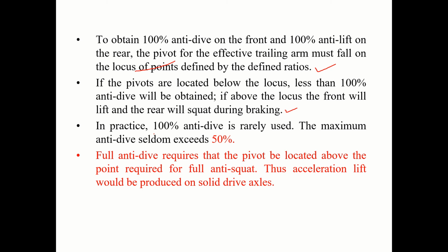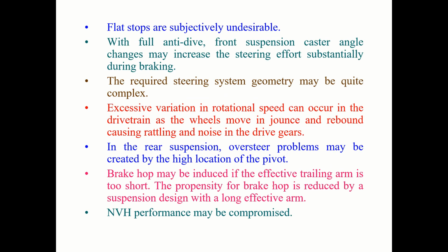In practice, 100% anti-dive is rarely used. The maximum anti-dive seldom exceeds 50%. Full anti-dive requires that the pivot be located above the point required for full anti-squat. Thus, acceleration lift would be produced on solid drive axles. So, flat stops are subjectively undesirable. With full anti-dive, front suspension caster angle changes may increase the steering effort substantially during braking. The required steering system geometry may be quite complex.